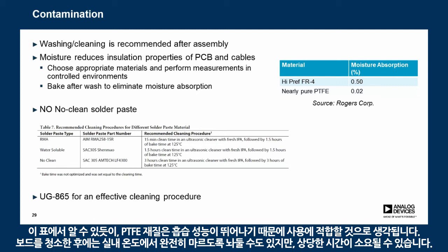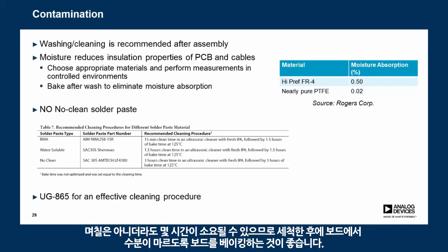After you wash your board, you can also leave it out to completely dry in room temp, but it's going to take a very long time. It's going to take, say, hours, if not days. So we do recommend baking a board after washing to drive out moisture from the board.